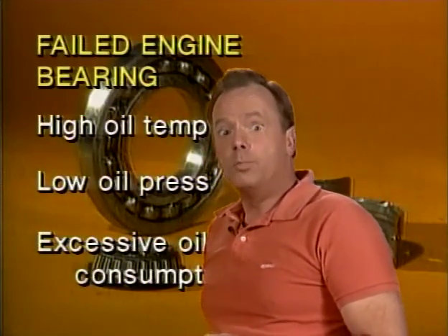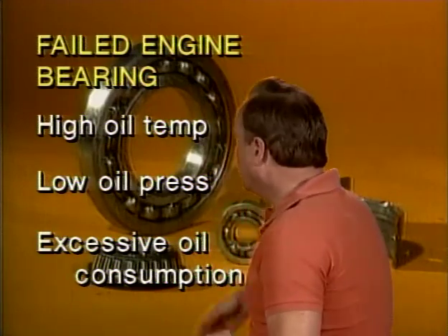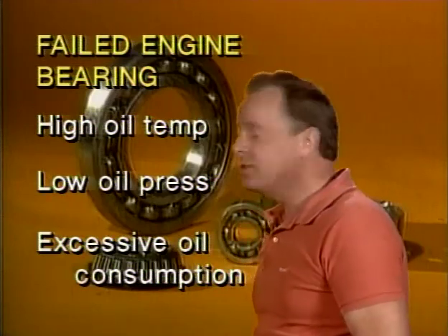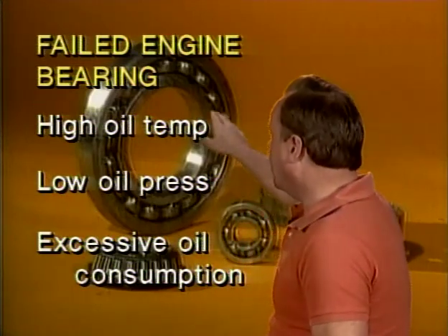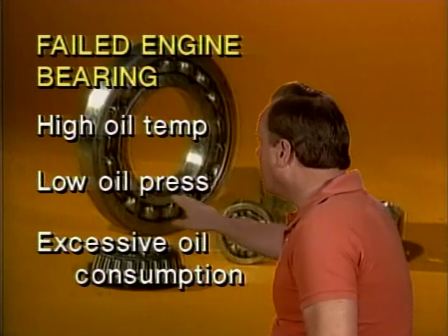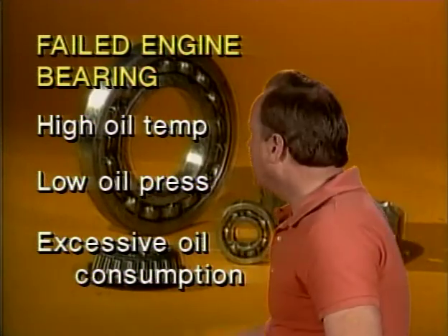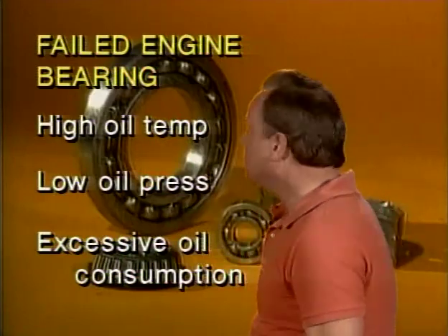What's the least likely indication? Well, the least likely indication would be low oil temperature, because high oil temperature is an indication of a failed or failing engine bearing. Other things that might indicate a failed engine bearing are low oil pressure and excessive oil consumption. Those are the things that are an indication of a failed engine bearing.